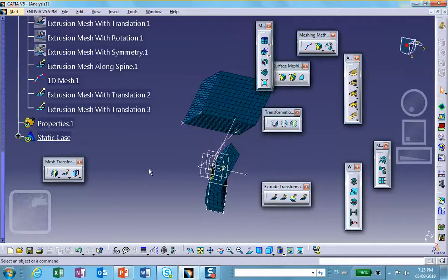Now, the one thing I have to tell you is that after you create all these meshes, there's really not much you can do with it in Catia, because Catia is a feature-based finite element program. Its FEA solver is feature-based. In other words, the restraints and load must be specified on geometrical features, on edge, on point, on line, on plane, etc. And here, we created the mesh, but we don't have any features. However, you can take this mesh and export it into some other package that allows you to put constraints and loads on nodes, and that can be done.